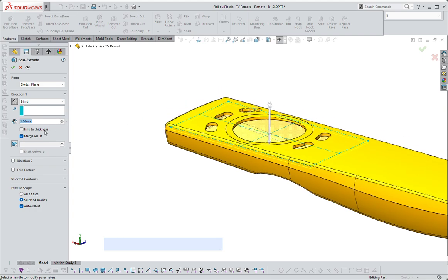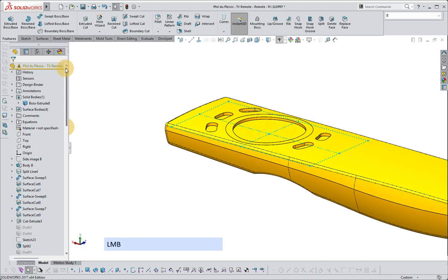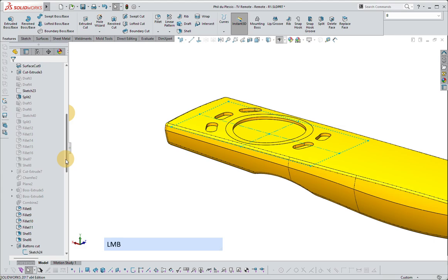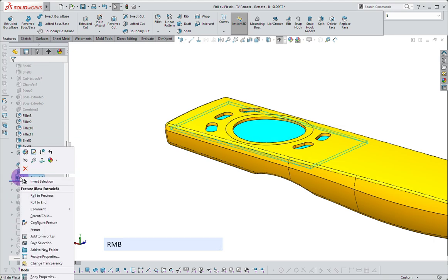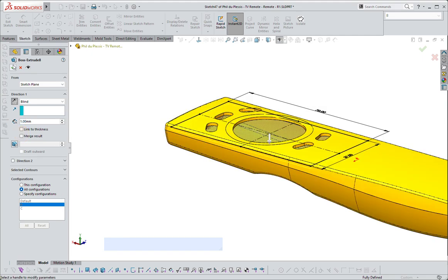Okay, and up to this point, we've ignored this merge result button. We've ignored that one. What that does, I'll show you what it does in case this happens to you. It merges all three of our models into one. That's not what we want. So I'm going to go back in here and I'm going to unmerge this, and now watch what happens.